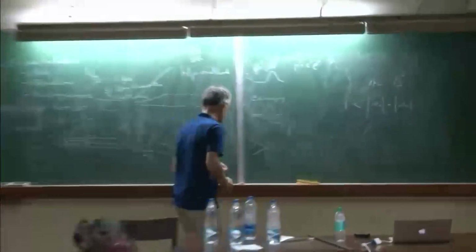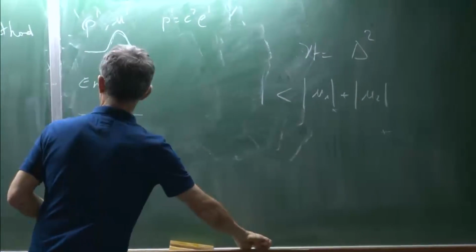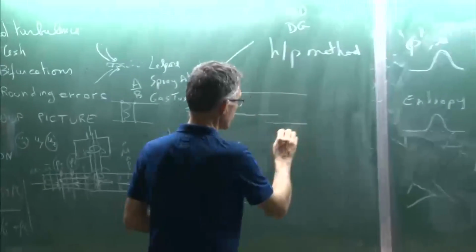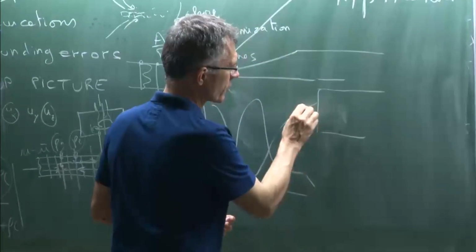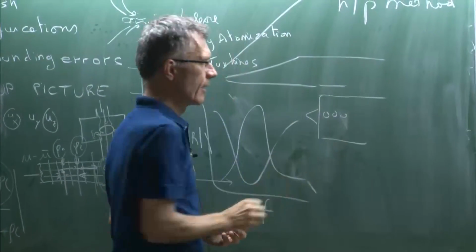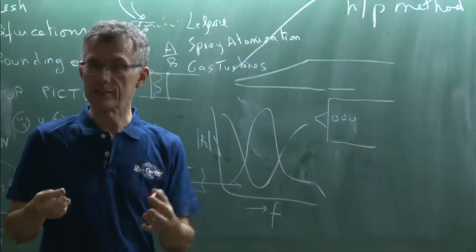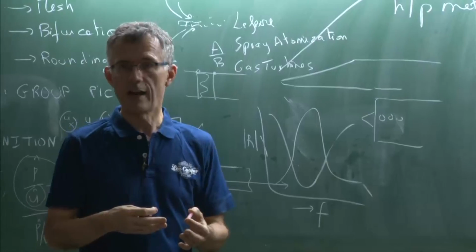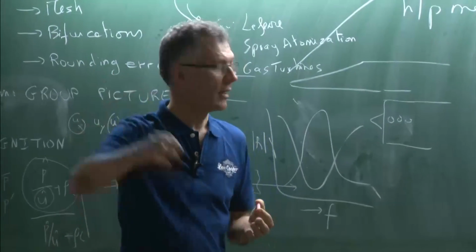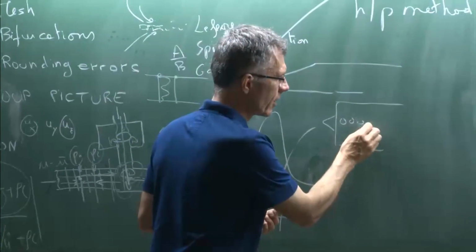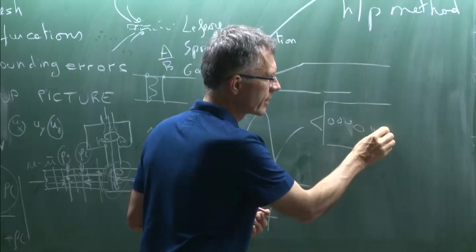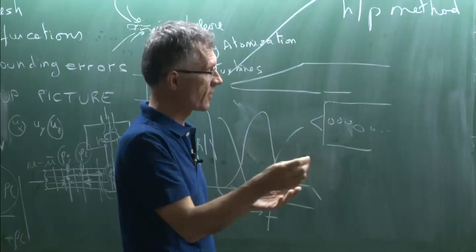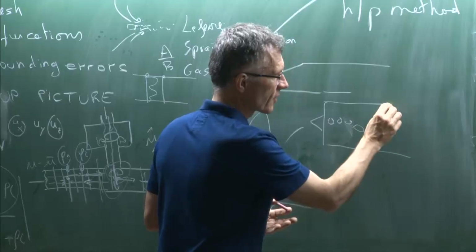That's what we said when we talked about entropy waves: when a combustor is long, the entropy waves are created here, but they are dissipated by mixing, which is much more efficient to kill them than acoustics. Acoustic waves travel a long time, but an entropy wave is really a hot spot, and it will get diluted with the fresh gases, or even with the burnt gases.